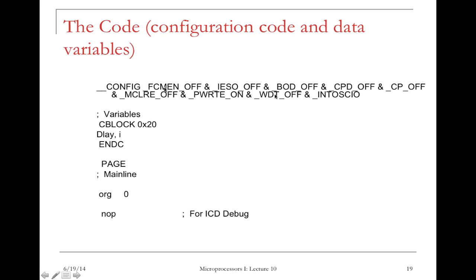Probably I will turn off my watchdog timer feature for this program. So there are a lot of things you can control from the hardware level, and you're going to use these configuration bits to do that. These are not PIC assembly language instructions. This is just specific to controlling the features and operations of the PIC chip. It's not the user program that we designed.